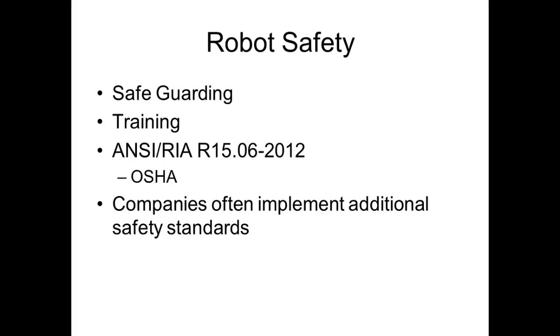So NFPA 70, the NEC, does not cover your safety. It covers the safe installation of electrical equipment. Now, of course, probably 90% of the time, if you install stuff safely, it's going to keep you safe. So what they did is they came out with 70E. If you go to work for a company in the state of Alabama, you're going to hear about 70E. 70E is rules that protect the employee.